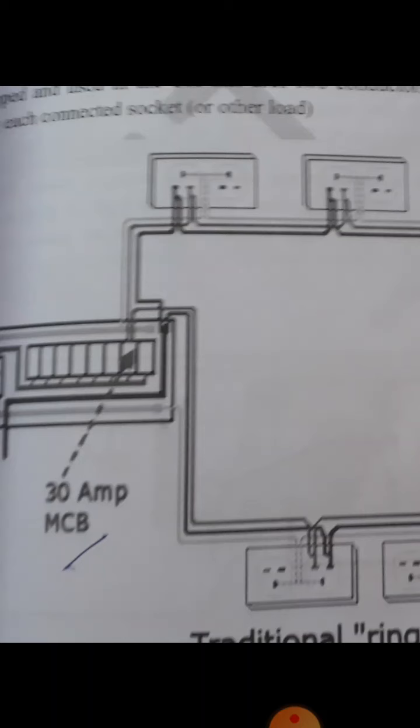So in Gulf standard wiring, power sockets are separate and not mixed together with lighting, because for lighting we use 2.5 mm square wire and for power sockets we use 4 mm square. For power sockets we use ring circuit wiring, but lighting is only normal wiring with 3 wires: 1 phase, 1 neutral and 1 earth. But the ring circuit has 6 wires in the same circuit. 6 wires means 2 of the same phase, not different phases: 2 wires of red phase, 2 wires of neutral and 2 wires of yellow-green earth. All of you, I think, are clear about this.